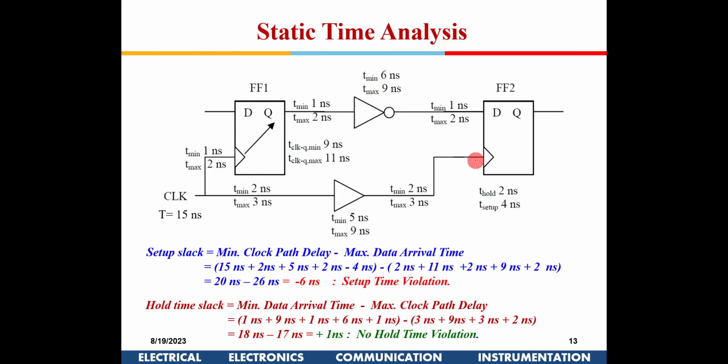Now we are going to talk about max delay in the clock and minimum delay in the data, the other way around from setup, for the worst case scenario. So minimum data travel is about the same edge. By the time the clock is coming here, the data should not change here. Same clock, we are not talking about two different clock edges.